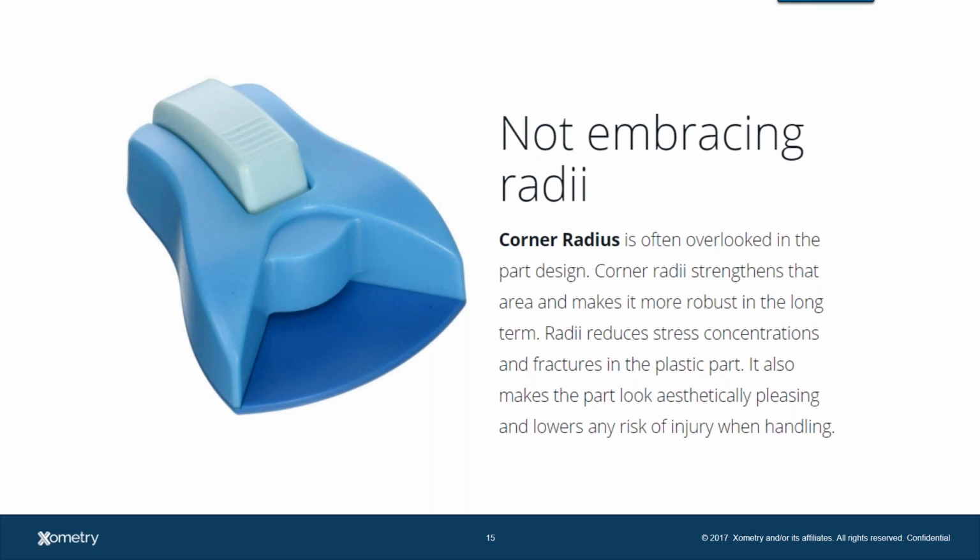Two, you're mitigating things that can happen when you're talking about these acute angles, these vertices, where there may be a fill issue or maybe an unpredictable result due to sink, due to uneven wall thicknesses, due to things that internal corner can cause issues with.